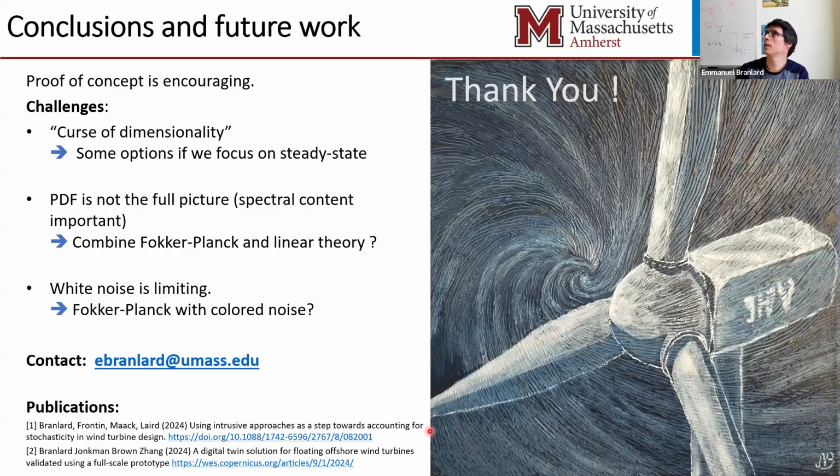What I have in mind right now is, when we do wind turbine simulation, we do them for a given wind speed, a mean wind speed, and then we have turbulence on top. And so we are in this part of the wind spectrum where we are in the turbulence part of it. The large scales, we always discard them in this approach. Whatever is larger scale than 10 minutes, we don't really care much about, or we account for them differently through different design cases where we do extreme wind and things like this. So my short answer would be the scales we're looking at are whatever turbulence scales we have in 10 minutes.